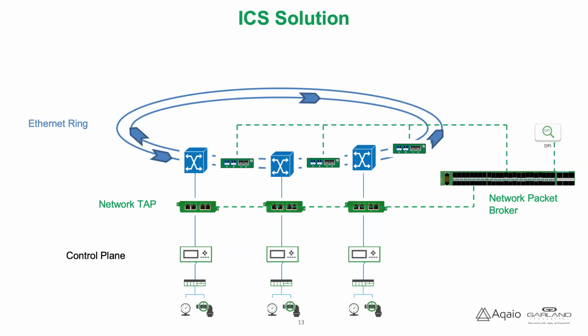And this often happens in power generation plants. Each one of those verticals could be some form of turbine or something that was reporting up to a control system. So if we tap into that backplane there, I can then take that data off in another way. The switches that I have there, I have another choice really. I could either again mirror, and I could mirror out and bring that in via, as I've shown here, a tap, into a packet broker and still have that unidirectional data diode side of things, or I could come down and I can tap my links at a lower level.